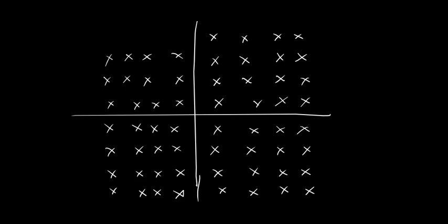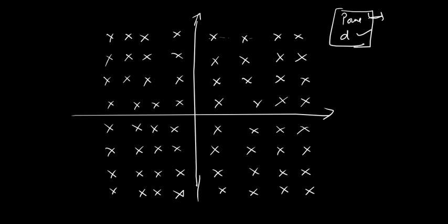What things do you have to control? Power and distance. What does power tell? Average energy. You have to control the average energy and you have to control the distance. Energy will decide how energy efficient your system is, and the minimum distance will decide how reliable your system is, or how well it performs over noise.